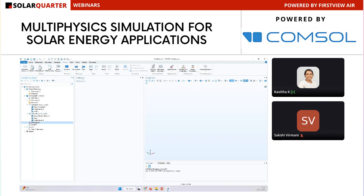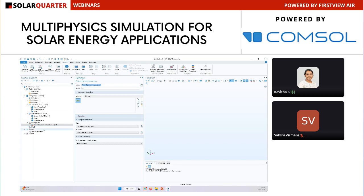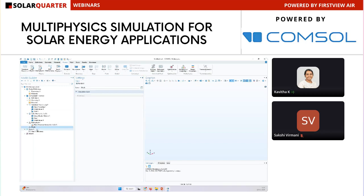You can define the multiphysics. In our example, we are going to have two physics, so we can check whether we already have a predefined multiphysics. We have a fluid structure interaction, so we can use this multiphysics node. Then you mesh the geometry, then you compute your study, and then you visualize your result. So this is the modeling workflow.